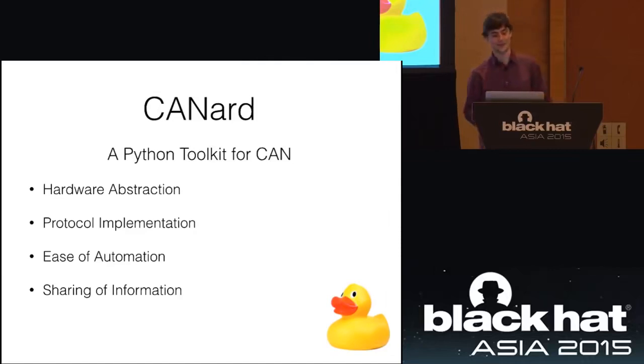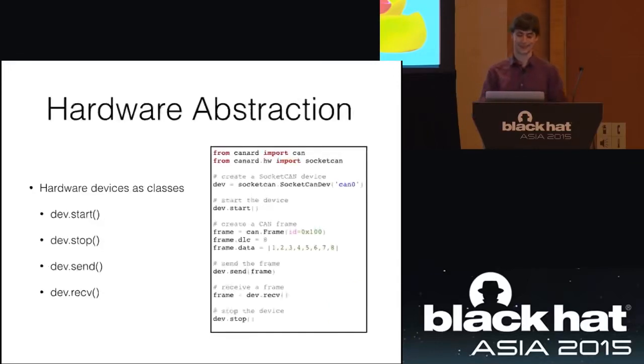But the idea of this software is to provide some hardware abstraction, to implement the protocols that are really common on these CAN buses, to ease automating, looking at CAN buses and sending and receiving messages, and also just to make it easier to share these things. If the hardware is abstracted and you have any supported tool, now I can give you a script and you can just run it and it works. Rather than, oh, well, I wrote this for Peak and it doesn't work on other tools, or whichever way around it is. So just by making something that's not paid for by any of the people who actually make those tools means that you can make it compatible with all the tools, which is nice.